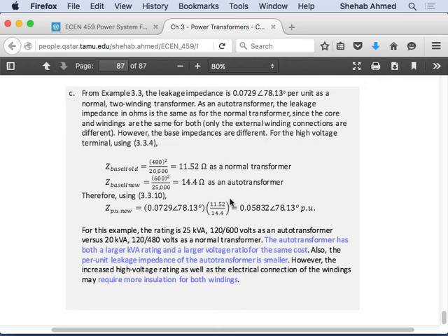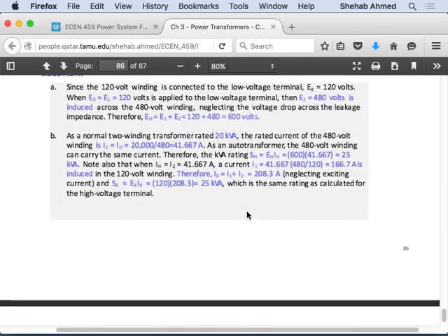So they are good for transmission level applications, where the isolation can be compromised. It's okay because nobody's up there touching these things. They know that the only thing that will make these transmission lines at this voltage level hit each other is wind, and they've already designed for that, or lightning, and they already protected against that. Right? There's no unknown circumstance. So it's okay to use it up there, and nobody will go up there and die. It's fine to use it at these high voltage levels. So this really wraps up the chapter.